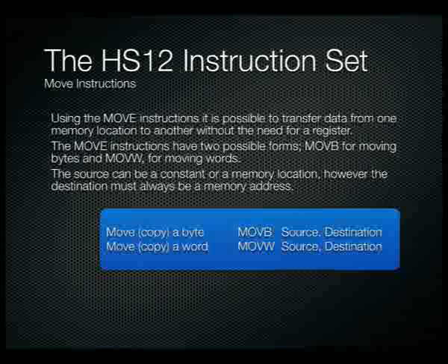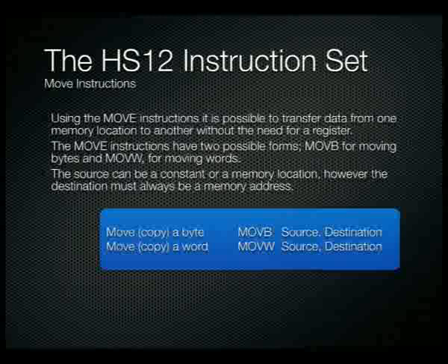Okay, so another really good instruction that people seem to overlook is the move instructions. People still tend to want to load values into registers and then store those values back to some memory location, but you don't have to do that. Using a move command, you can simply move data from one memory location straight to another, or you can move an immediate value straight to a memory location without having to go through the two-step process of a load and a store.